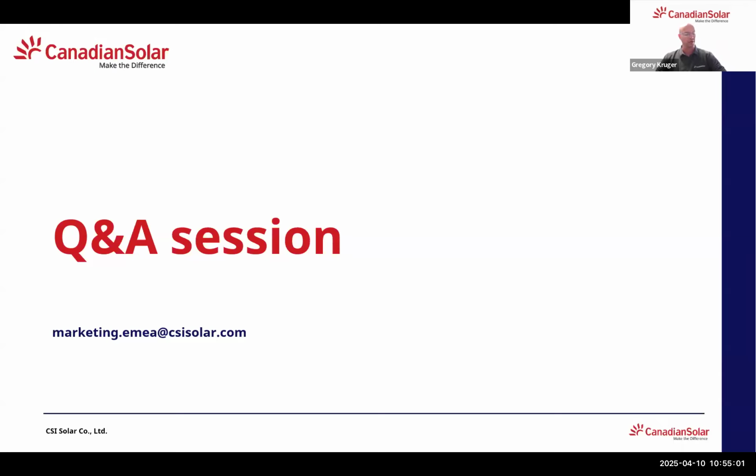Let's have a look. So is the EPCube listed on the City of Cape Town's approved list? Yes, it is. The EPCube is NRS 097 approved. And we did recently receive confirmation from the City of Cape Town that they will add the EPCube to the list. I know a lot of other municipalities in the Western Cape and rest of SA follow that list, so it's definitely approved. Then what is the maximum kilowatt peak PV power for the EPCube? So that will be 10 kilowatt peak, 5 kilowatt per MPPT, and 16 amp max per string.